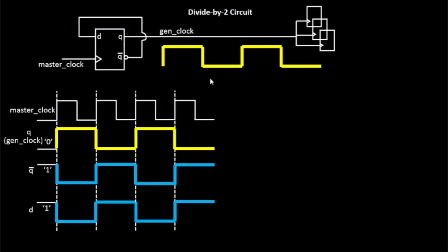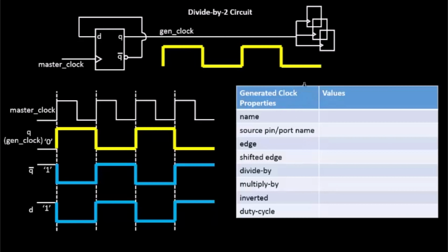So we have to construct this waveform, or code this waveform, in such a fashion. There are some syntax and semantics to it. So you have to code this waveform in a syntactical manner so that the following circuits will understand it. So how do we do this? We have got a special setting called generated clock. We can create a generated clock at this point, which is derived from this master clock, because on a functionality basis, the generated clock is derived from the master clock.